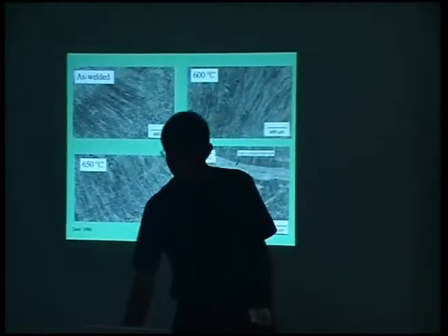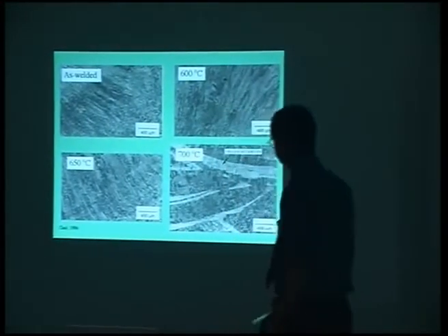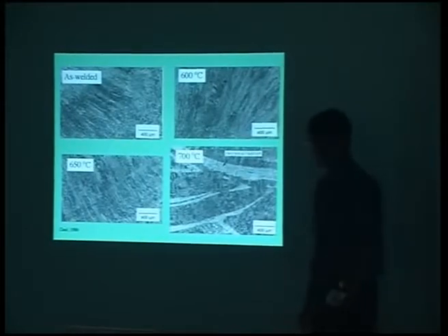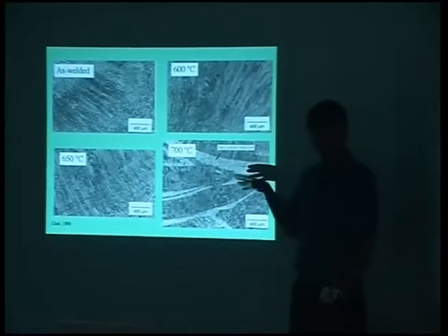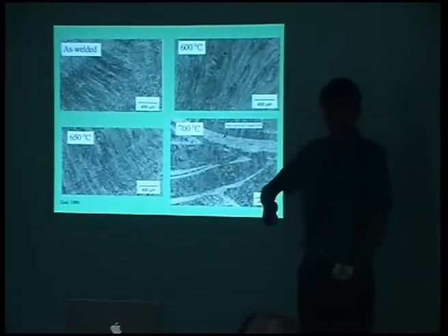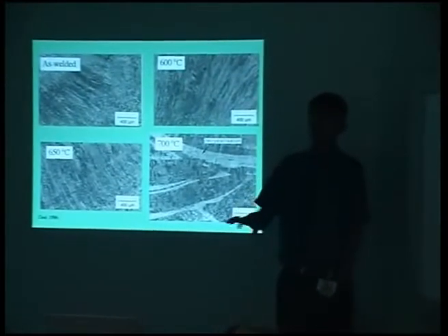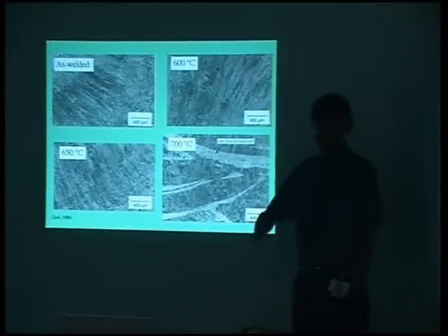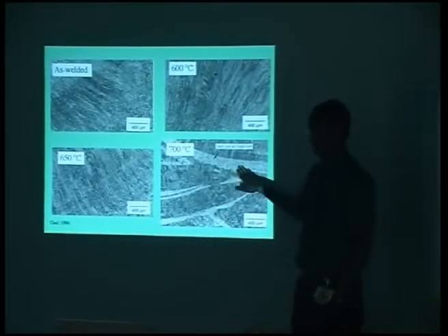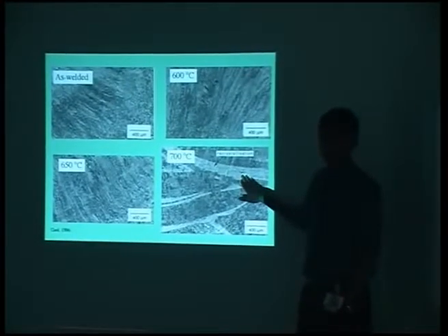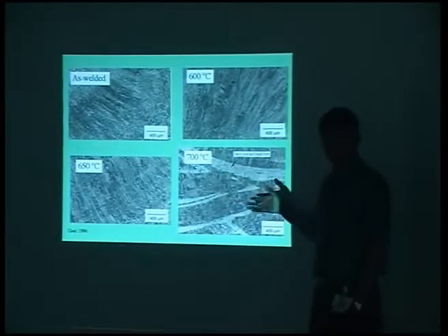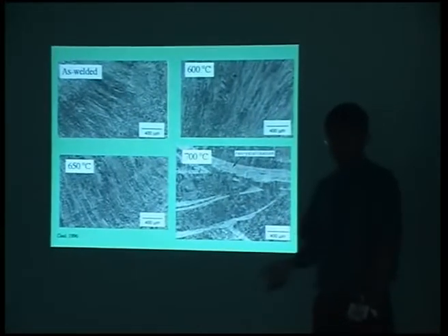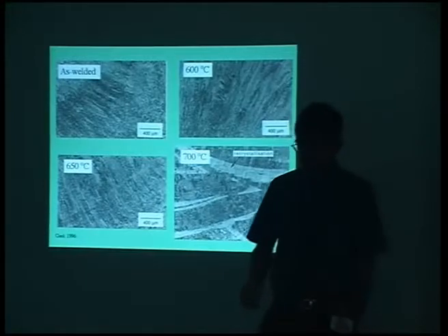Why is the recrystallization in bands? Is it some segregation effect? Yeah, you see, this is a manual metal arc weld, and because a human being is not completely steady, the solidification rate changes in different positions, and therefore you get solute banding. Okay. And therefore we have recrystallization in the solute depleted regions of the weld.